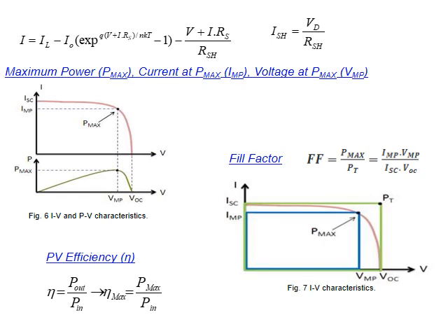Now for maximum power, I mentioned before in the IV characteristics that it's plotted in this curve, okay? By the way, it's supposed to be plotted in this way, but the shaded part here is lost because of the losses inside the cell. Here is the short circuit, here is the open circuit voltage, but the maximum is supposed to occur somewhere here where we have the maximum or peak current and peak voltage, okay? The PV characteristics based on this can be plotted in this way, and again it peaks at this point, okay? Now efficiency, we discussed: output over input.